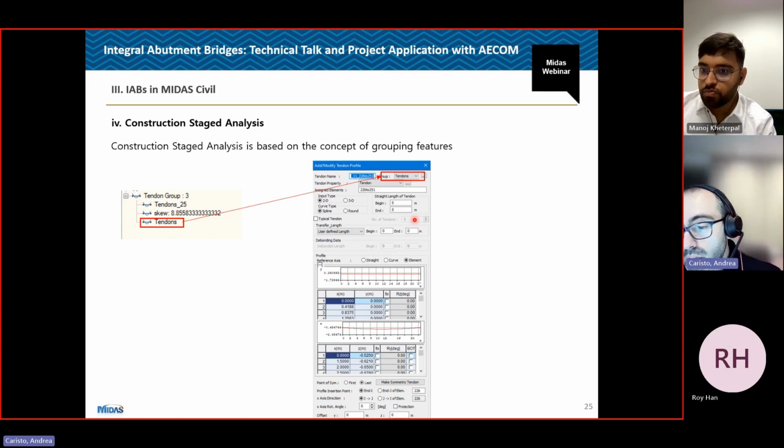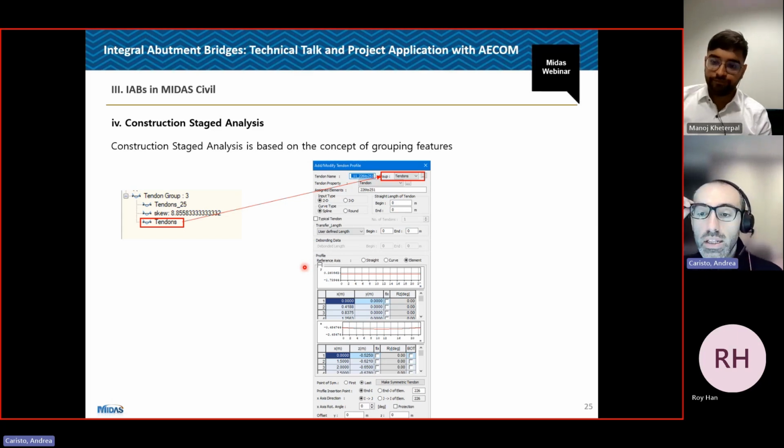Now, you cannot just always follow the bending moment diagram, because sometimes, particularly with prefabricated beams, there are costs associated with fabricating the beam. And so sometimes the precast yard doesn't have the possibility of placing the tendons, or strands, monostrand let's say, in the optimal way.